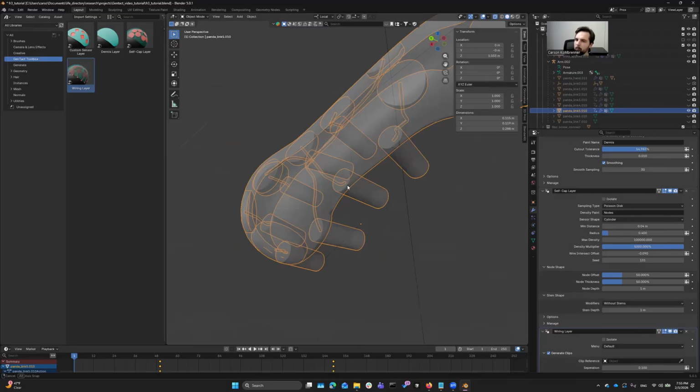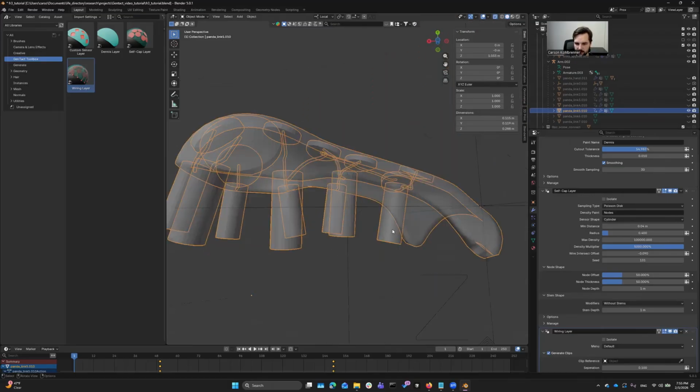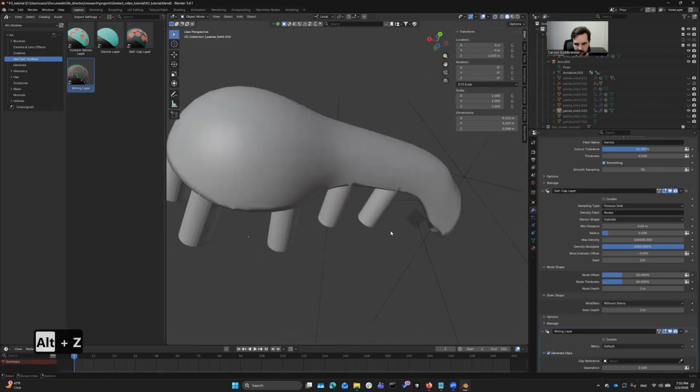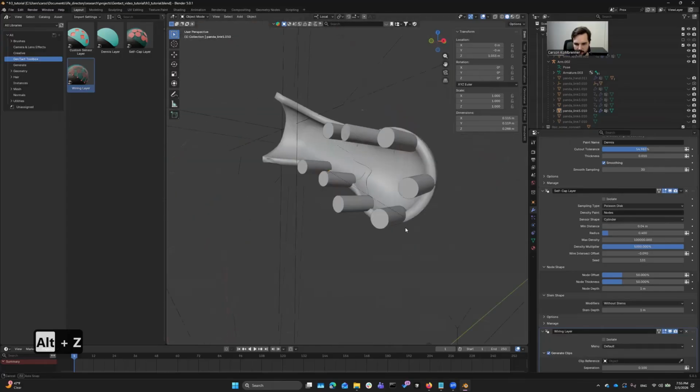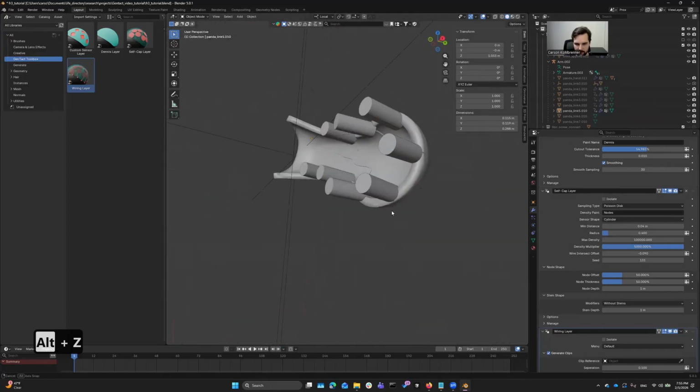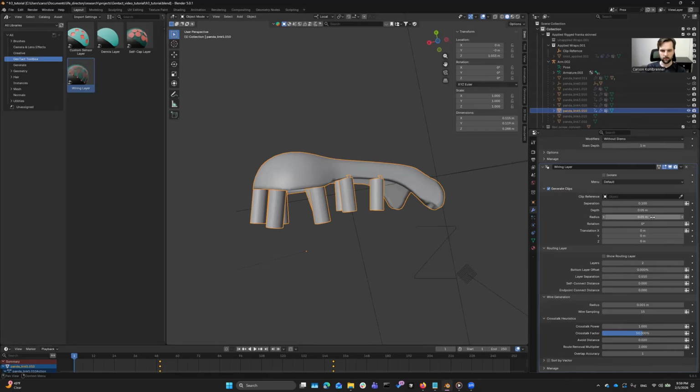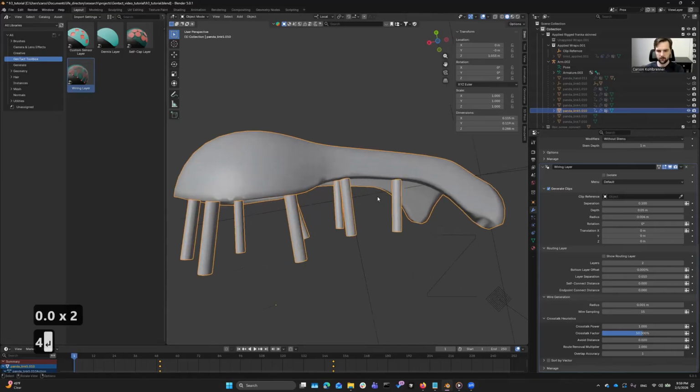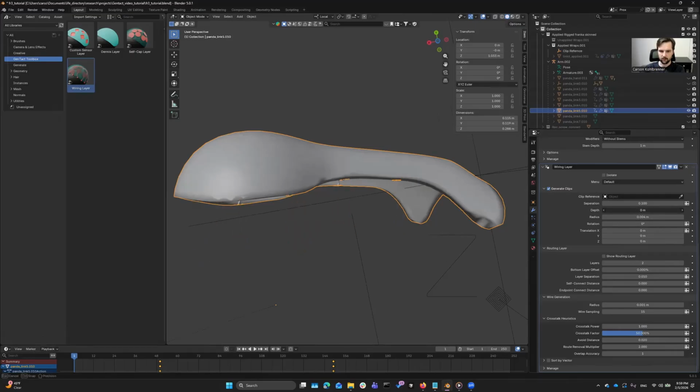Another thing I can clean up is that these clips are a little nasty. If I look at what we'll actually be printing, they're way too big. They're sticking out way too far. I'm going to lower the radius by about, I think 0.004 is probably good. Make them not as long.